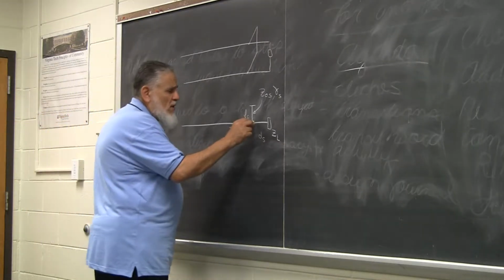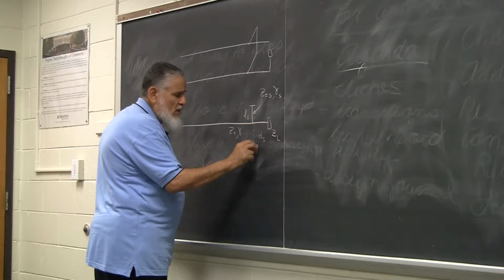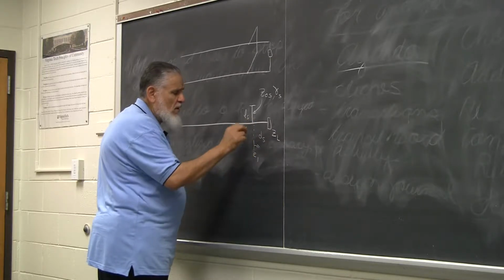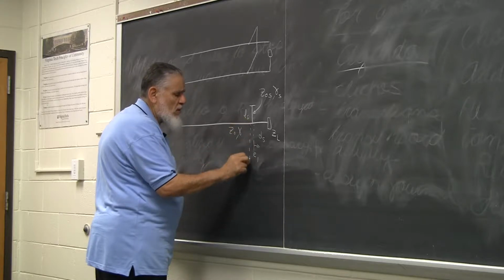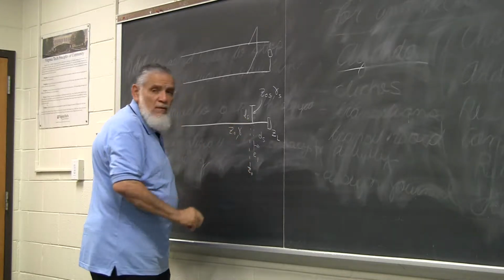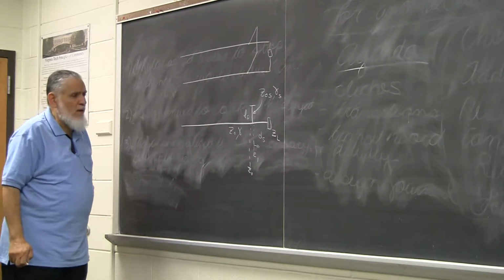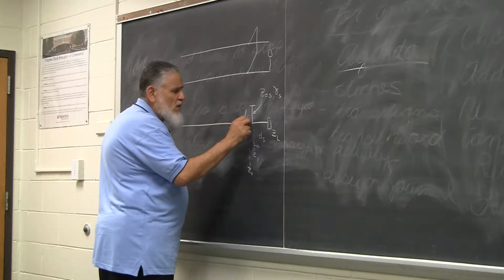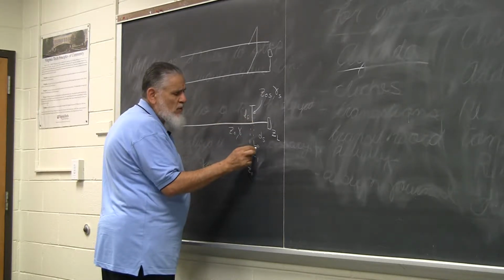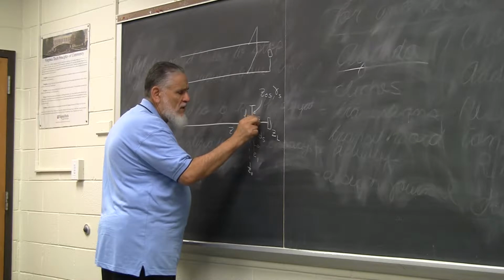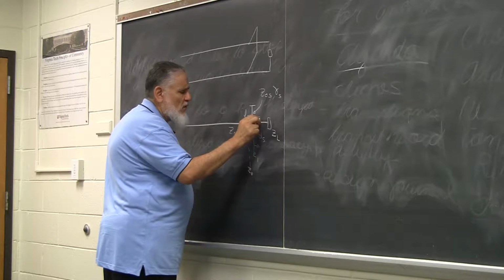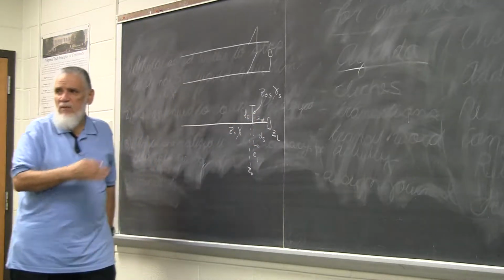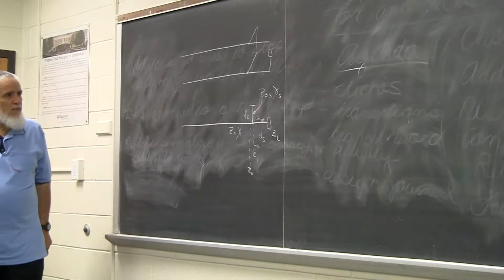So the point is, at this location here, we have an impedance which we call Z1. At this location here, supposedly the impedance now has become Z0. And Z0 is going to be matching the combination between Z1 and what we have here as Z of the stub. If I call it ZS, it would be ZST. All right? Because ZS is typically the source impedance. So, Z of the stub.